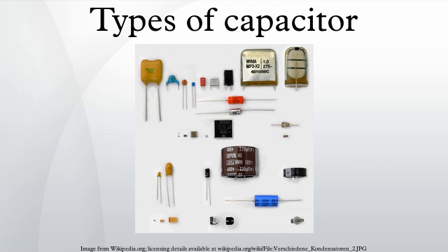Supercapacitors are divided into three families, based on the design of the electrodes. Double-layer capacitors are with carbon electrodes or derivatives with much higher static double-layer capacitance than the Faradaic pseudocapacitance. Pseudocapacitors are with electrodes of metal oxides or conducting polymers with a high amount of Faradaic pseudocapacitance. Hybrid capacitors are capacitors with special and asymmetric electrodes that exhibit both significant double-layer capacitance and pseudocapacitance, such as lithium-ion capacitors.